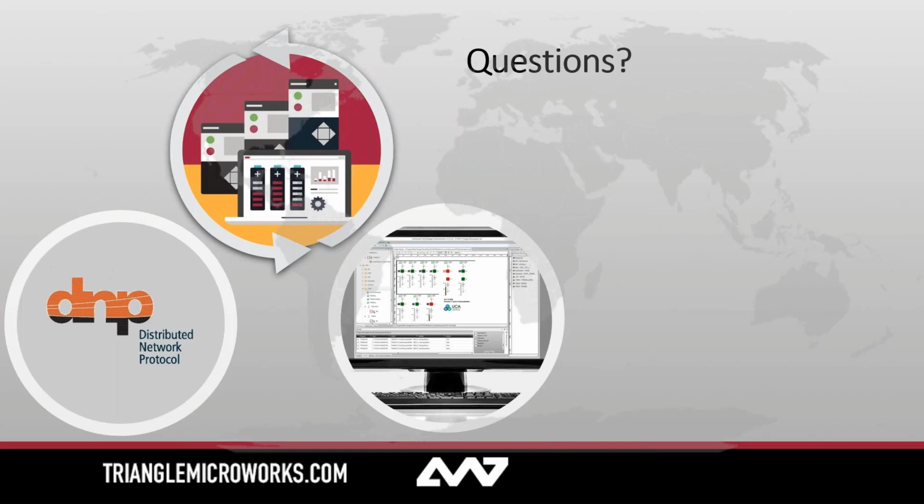Does DTM support line animation in a single line diagram? I would say yes. I'd have to know a little bit more about what visuals they're looking at. From the single line diagram I showed off today, I didn't necessarily point it out directly, but red essentially meant hot, it's energized, and green meant not energized. So when I did the breaker failure, you'd see at the very bottom that the transformers were no longer energized. That's one of the types of animations we do.